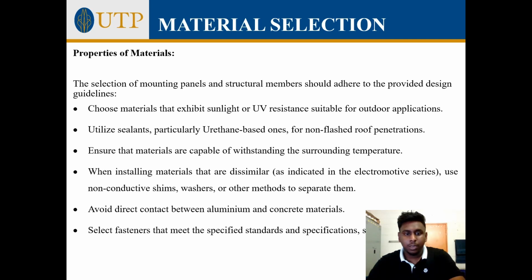When installing materials that are dissimilar, use non-conductive shims, washers, or other methods to separate them. Avoid direct contact between aluminium and concrete materials. And finally, select fasteners that meet the specific standards and specifications, such as stainless steel.